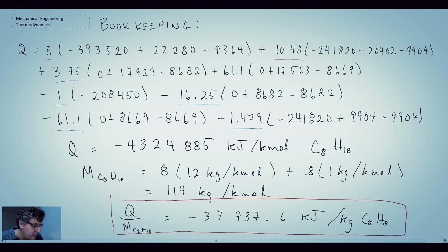So that concludes the example problem of applying the first law to a system with reaction. You can see it's kind of long and laborious, with a lot of places to make little errors, so you've got to be careful. But what I would recommend is going through the procedure that I did: starting with the stoichiometric balance, getting your reaction equation, then writing out that table with all the values, and then proceeding to apply the first law. By doing that, you minimize your possibility of making small errors or mistakes while you're solving the problem.